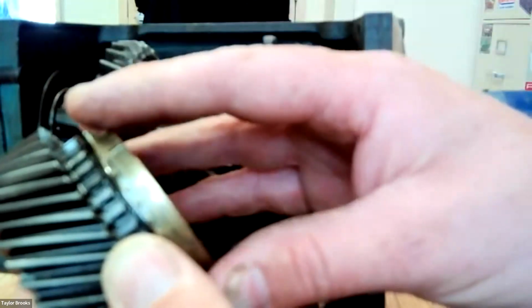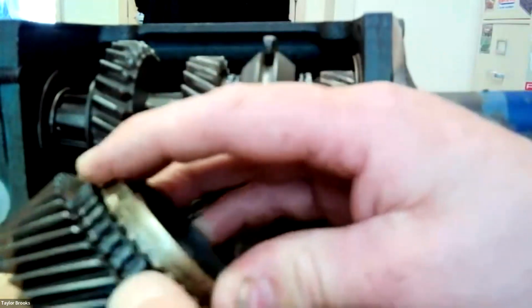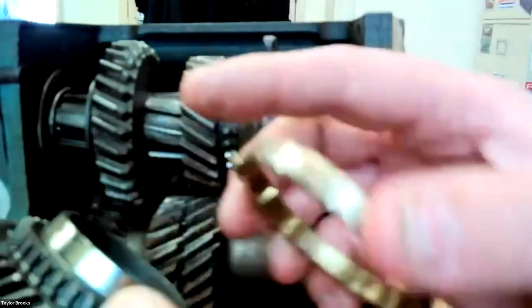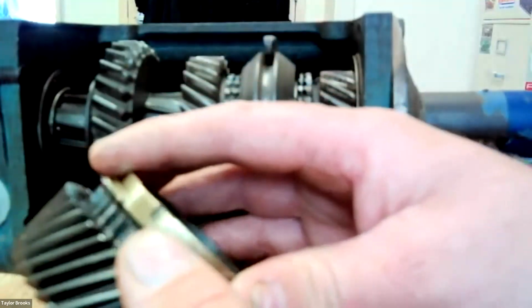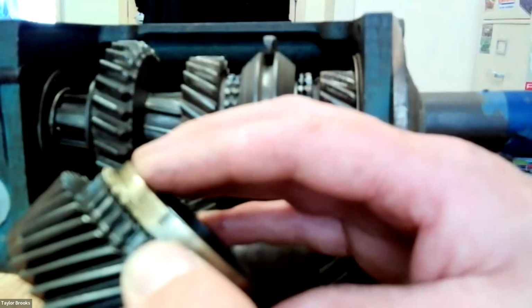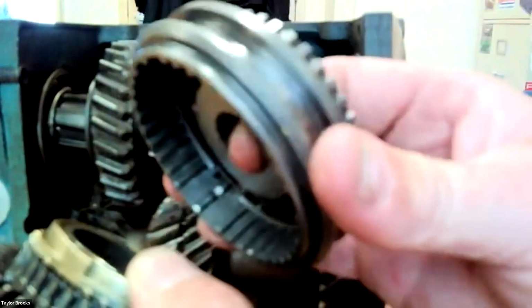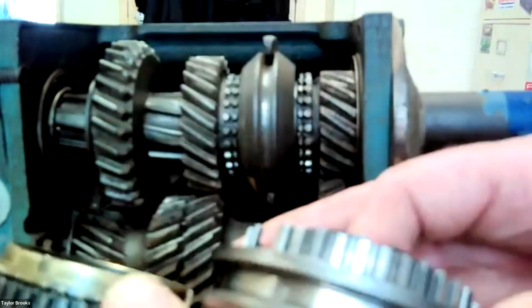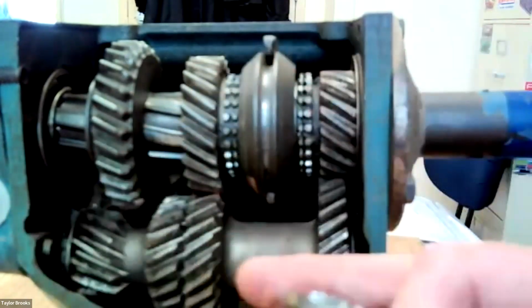So as the slider, because the hub is missing, this can move freely, but as I put pressure on it, it locks into the gear, and I can't spin it independently. That's because these little grooves grip onto this cone right here. And that starts to get this gear and the hub to spin at the same speed, to where these teeth get locked into the slider's teeth as this slides over. So the slider is going to be partially engaged on the hub, but primarily engaged on our dog teeth for the speed gear and for the blocker ring right here.